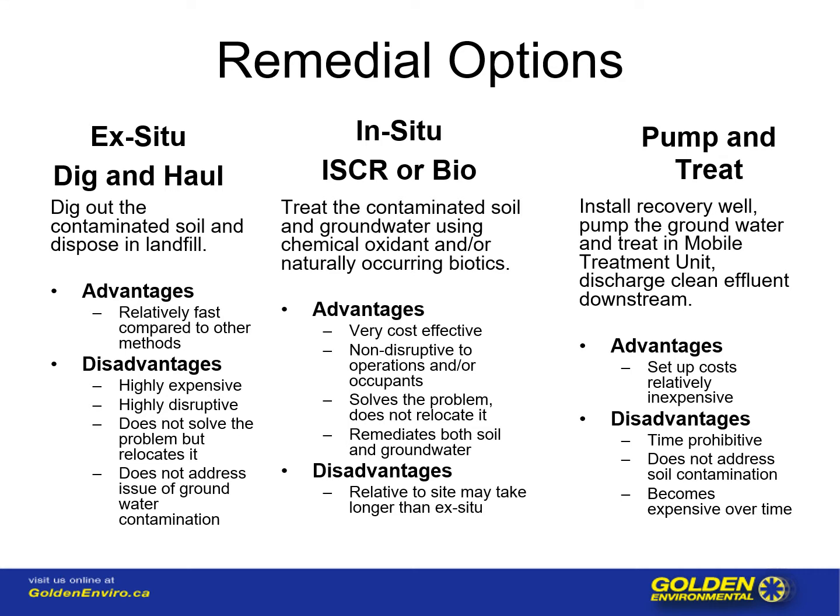Pump and treat systems are also used for hydraulic containment in order to stop contaminant from moving off-site. By depressing the water table in one central area, it creates a funnel effect containing the contaminant. This can be very advantageous during an in situ remediation process as well, as it helps to contain the contaminant as well as keep the oxidant within the contaminant zone.